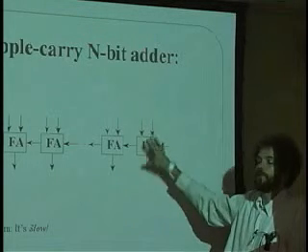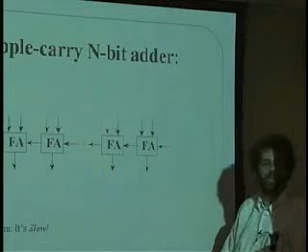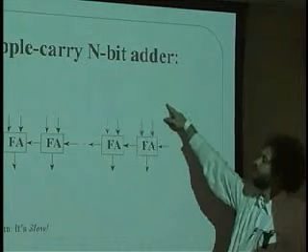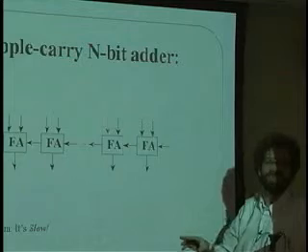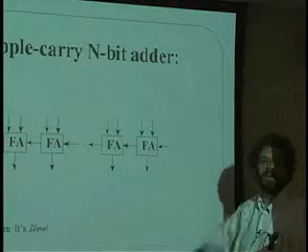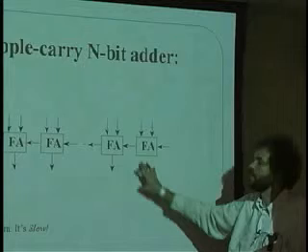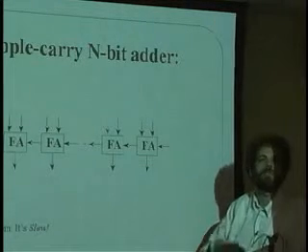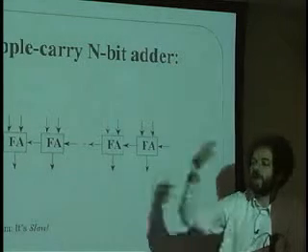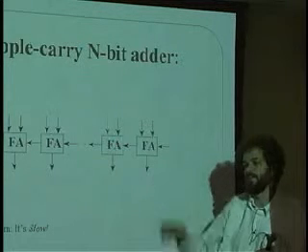You can actually build a system with no clock at all. They're called self-timed systems, where in addition to the data that goes into an ALU like this, you have a start pulse that says, okay, go. And what comes out of the ALU is not only the answer, but a finish pulse saying, I'm done. As soon as that's done, the next piece of circuitry that depends on the data is triggered, saying, okay, you start. These little start pulses chase each other through the circuit and loop back and start all over. The system has no clock at all other than these start pulses going around and around.